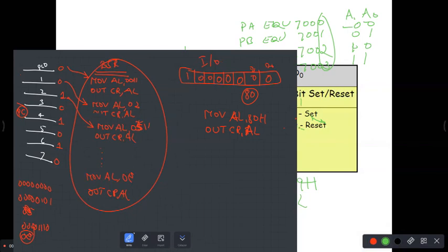What will these two statements do? This will set your 8255 in the output mode, where port C is configured as output. Now this is done only once. Now you have to put this data into port C. You just have to put the entire byte, because in this mode you cannot access bits individually. Individually you can't make set reset; that's only bit set reset mode.